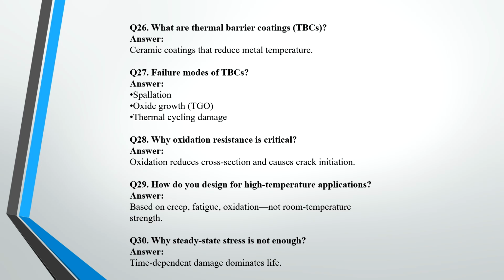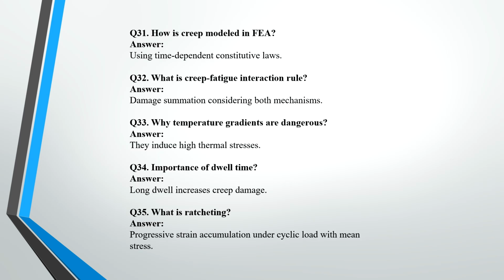Why is steady state stress not enough? Because it's time dependent damage which dominates the life. How is creep modeled in FEA? Using time dependent constitutive laws. What is the creep fatigue interaction rule? It's a damage summation considering both the mechanisms.